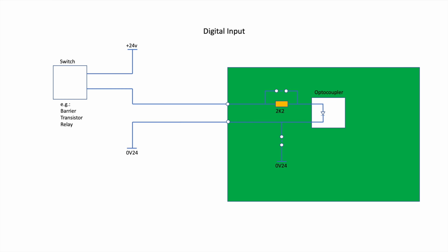If a supply voltage other than 24 volts is to be used, an external resistor of the correct value to restrict the current to 10 mA is required. Suggested external resistor values are 1K5 for 15 volts, 1K1 for 12 volts and 510 ohms for 5 volts. It should be noted that the switch element could be connected in the negative half of the circuit.